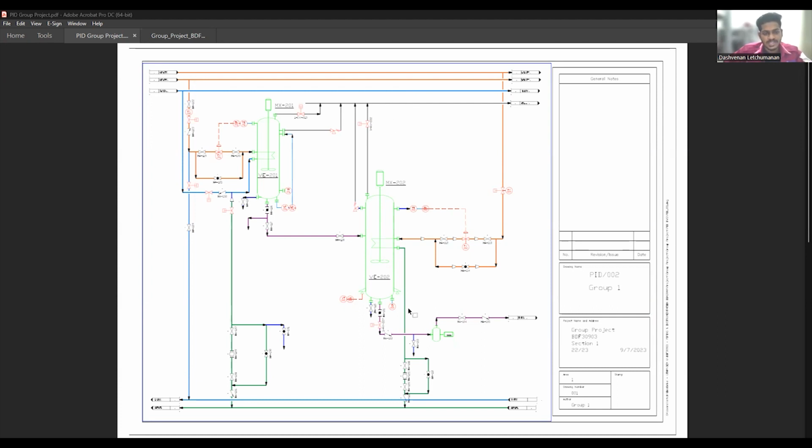The orange stands for the steam line, which transfers steam from the boiler house to the plant. It is divided into a 4-bar steam line and a 2-bar steam line, depending on the requirement of the process. VE201 and VE202 are involved in the preheating process, where the steam line transfers steam into the vessel. VE201 and VE202 are almost identical but not the same, where VE201 requires 2-bar steam while VE202 requires 4-bar steam.